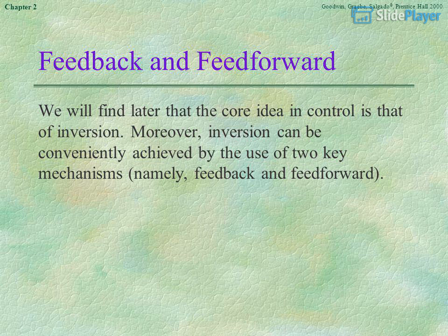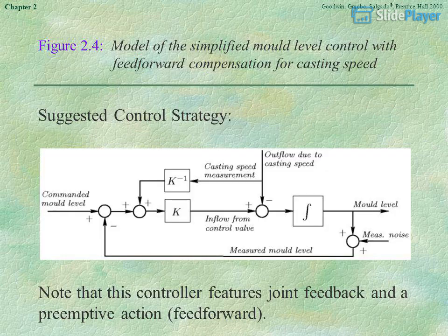Feedback and feed forward. We will find later that the core idea in control is that of inversion. Moreover, inversion can be conveniently achieved by the use of two key mechanisms, namely feedback and feed forward. Suggested control strategy. Figure 2.4, model of the simplified mold level control with feed forward compensation for casting speed. Note that this controller features joint feedback and a preemptive action, feed forward.